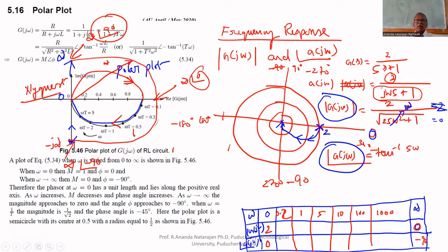What is a polar plot? If you substitute only the positive imaginary axis in the transfer function and get the plot, then it is called a polar plot. If you plot for the negative imaginary axis also, then you get the complete plot. The only thing pending is to draw the circle whose radius is infinity and the angle alone varies. That is nothing but a point at the origin. So if you combine all these three, then it is called the Nyquist plot.